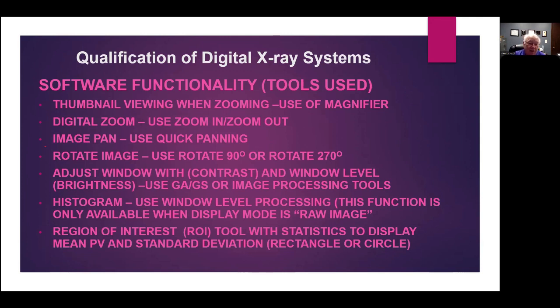Adjusting, this is probably the biggest value in digital radiography, the ability to window and level. So instead of taking 5, 6 different shots like we do in film sometimes, maybe 1 or 2 shots, and being able to window and level through different thicknesses helps you to save a lot of money that way.